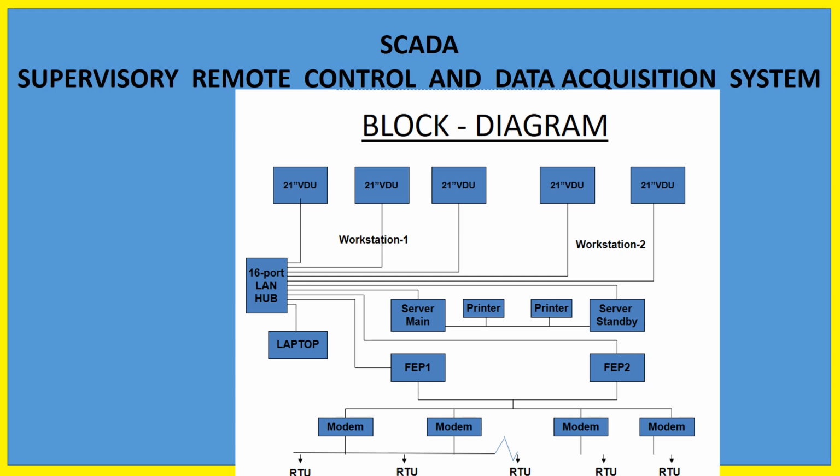This is the basic idea. Don't take it as perfect, it is some basic conception. And then you first start with the starting code. The company will select what they will start. Then step by step a packet is formed for telecommand and telesignal that will identify the switching post, the equipment, which interrupter, which CB, then what operation.